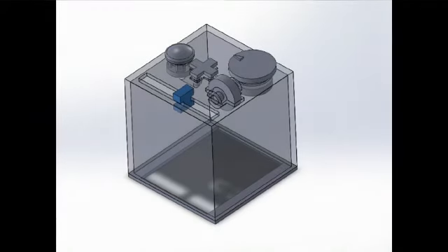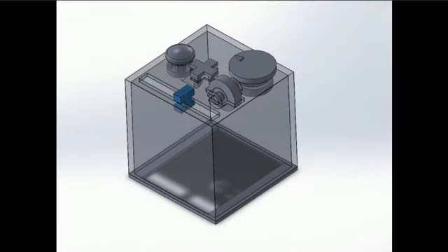And basically, the next step then is running computer vision. So we do this interactively. There's a calibration step where we basically highlight something in CAD and say, just move this component through its range of motion. And so in this case here, we'll just do blob tracking and find the minimum and maximum coordinates.